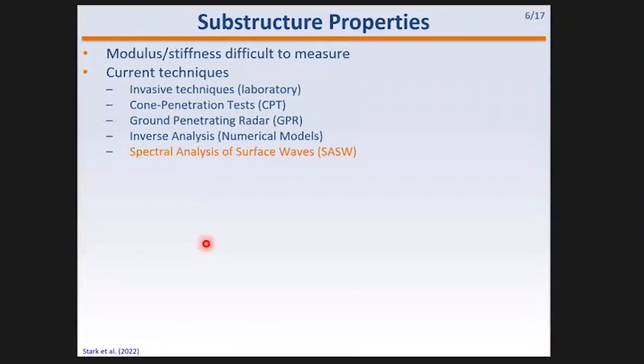So how do we measure modulus? It's difficult. Some current techniques, invasive techniques, and you heard about ballast sampling and testing. Some trying to correlate the cone penetrometer, ground penetrating radar, inverse analysis using numerical models, and I'll talk about that in a little bit. And so a while ago, we started with surface waves.